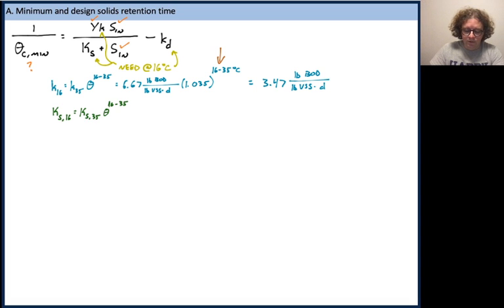Okay. We'll do that same conversion with our half saturation constant, converting from 1.8 grams per cubic meter at 35 degrees centigrade to 0.24 at 16 degrees. You can see that's an incredibly sensitive term, and we could have known that going in because that theta value is particularly high compared to what we're accustomed to working with. And I'll go ahead and just make that conversion from grams per cubic meter to 1.5 times 10 to the minus 5th pounds per cubic foot. And that's just to get the dimensions on that term homogeneous with the rest of what we're doing for this problem.